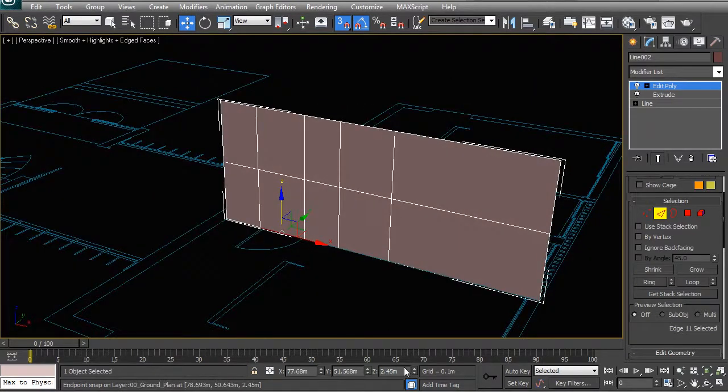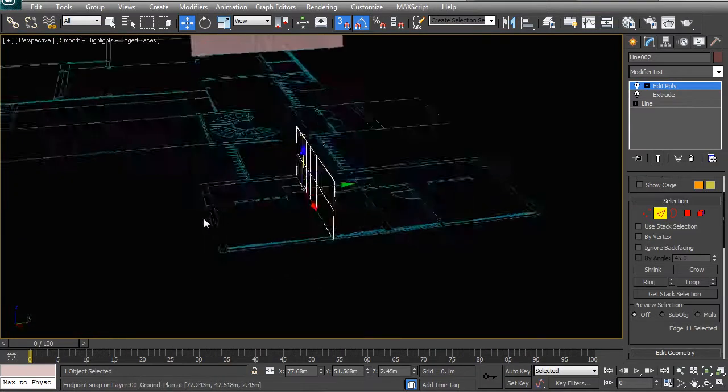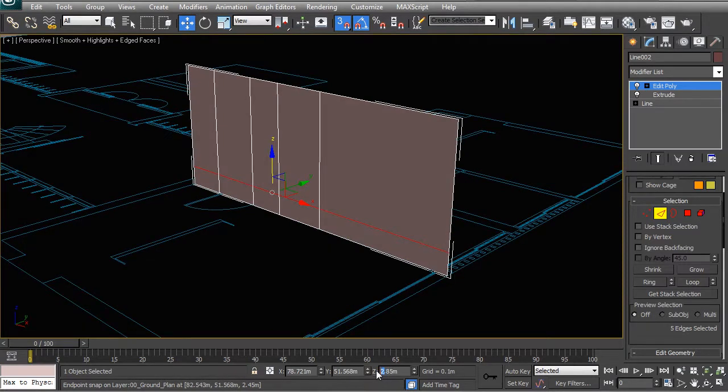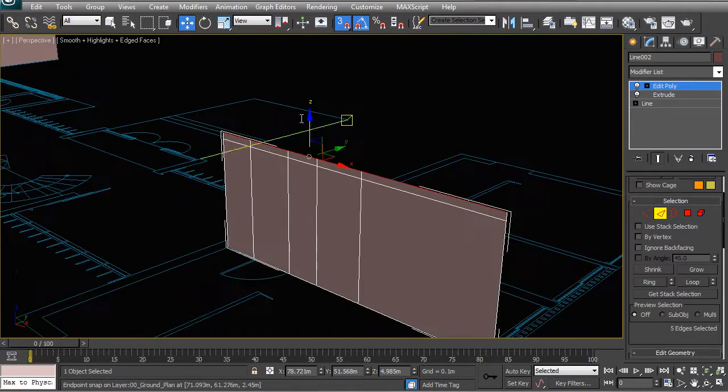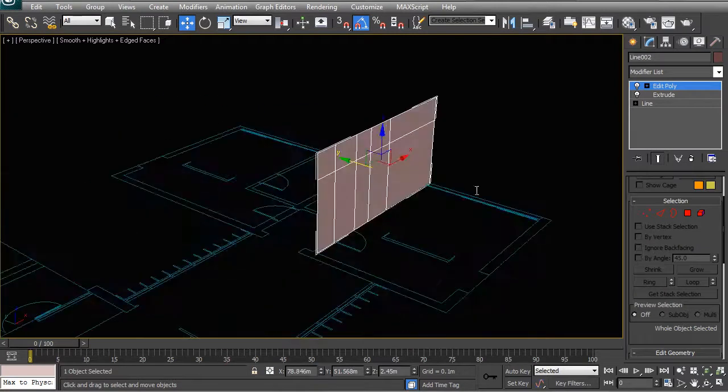So that's 2.45 plus 2.4, so it's a good idea just to know where your 0 is at, so that you can then start adding your numbers to that. So if that is 2.4, then we need to have a 2.85. So let's just select this line and move it up to 2.85. Sorry, that's 4.85. And we can now take this top line, and that can be moved up to the correct height based upon our elevation. But I'm going to look at those elevations later.